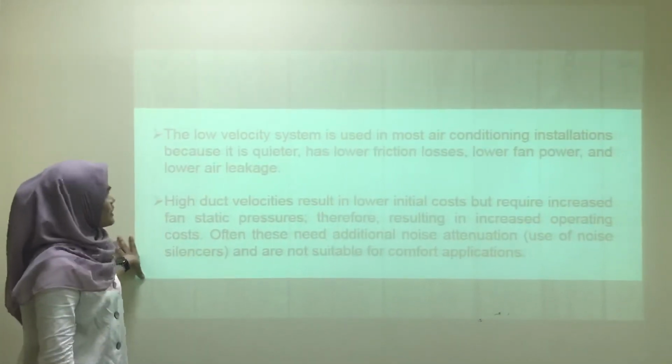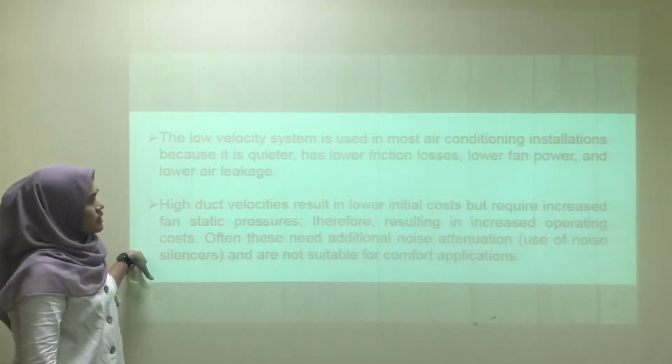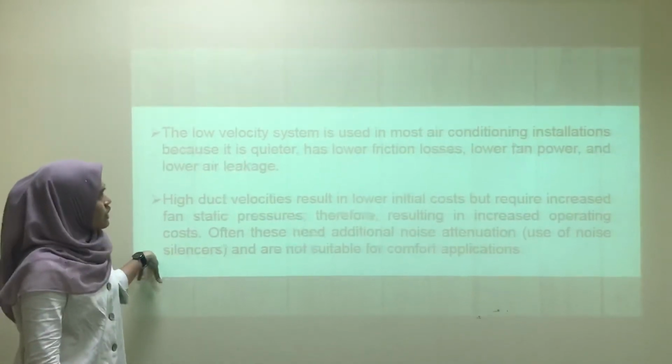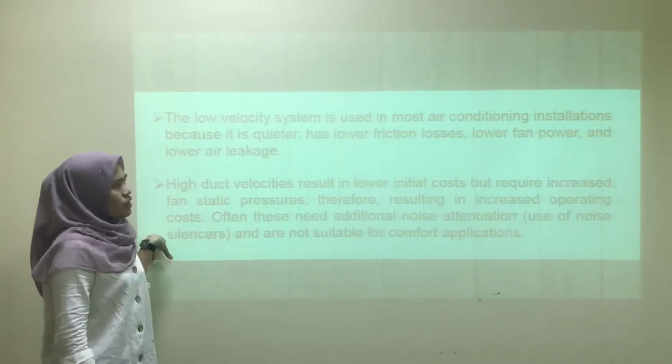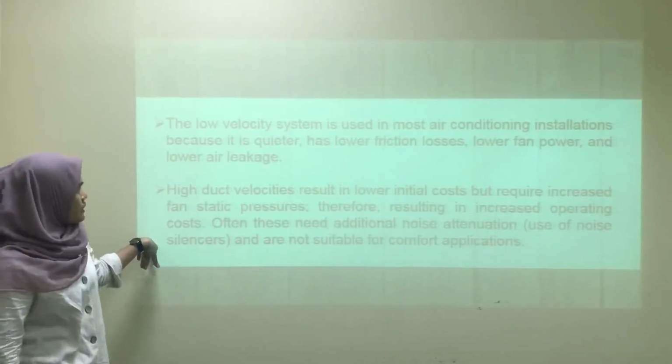The low velocity system is used in most air conditioning installations because it is quieter, has low friction losses, lower fan power, and lower air leakage.